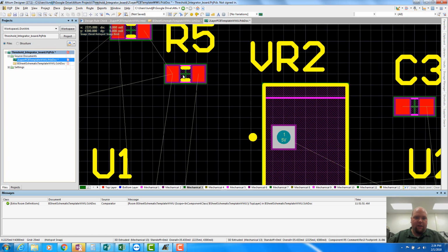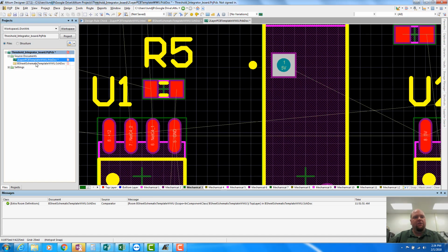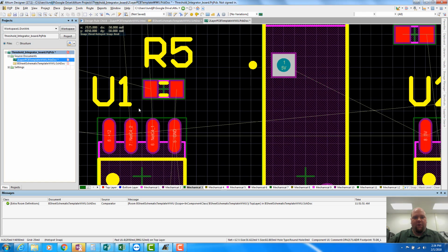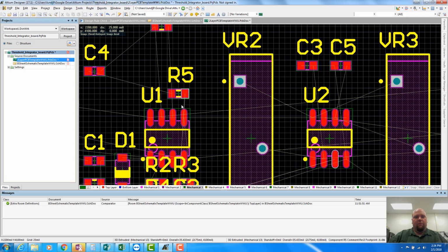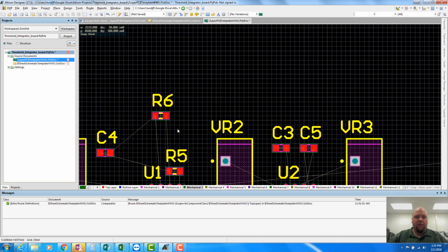I still want to keep this resistor over here, and eventually, I don't have it down here, but I definitely want to have a test point on this node, so I'll add that later. So we're not clustering this signal too close together. This net C2_2 probably should have a better name and a test point, but it's okay if there's a long trace here, because there's probably going to be a big fat test point here eventually.